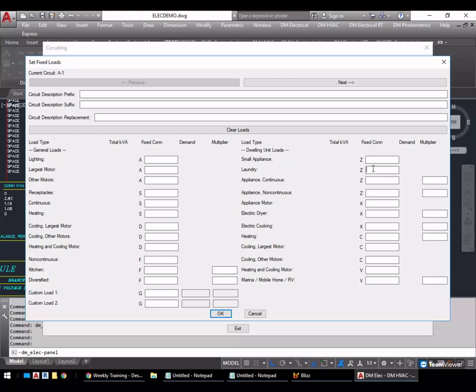Those actually get folded in to the general lighting. So the load based upon the area, we add these loads to it, and then you get to add your demand factor to that. There's also a statement that there's supposed to be 1.5 kVA for each circuit.